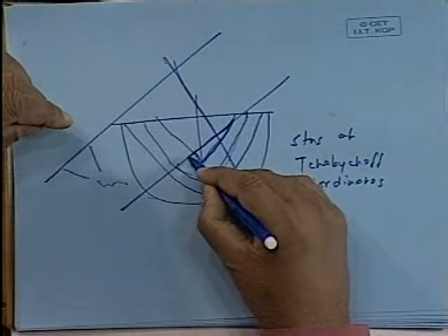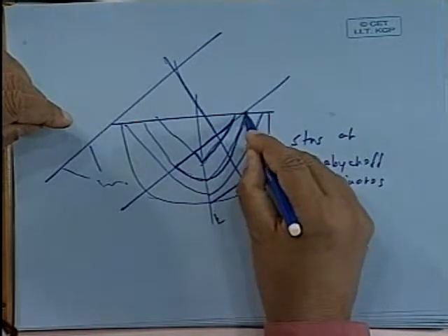It's a unique instrument. Actually it is gear based, and if you go around one particular thing, these gears will rotate to an extent proportional to the area. There are teeth here; as you go around, the teeth will rotate. If it is a larger area, it will rotate more, and this rotation is exactly proportional to the area covered. So when you are going to the second line, here you go this much, then you go here and go this much. Okay, then you get the difference.